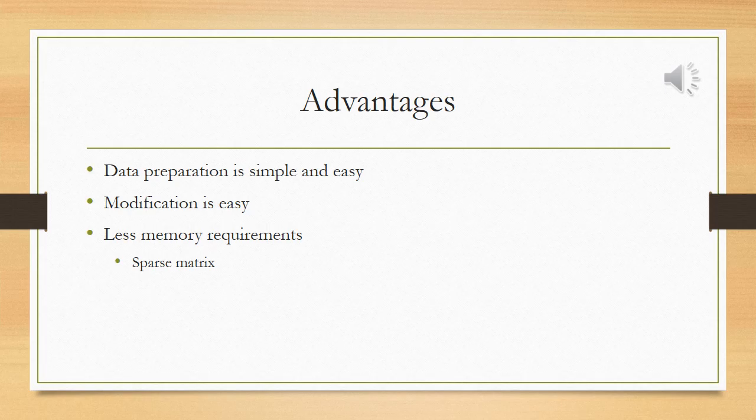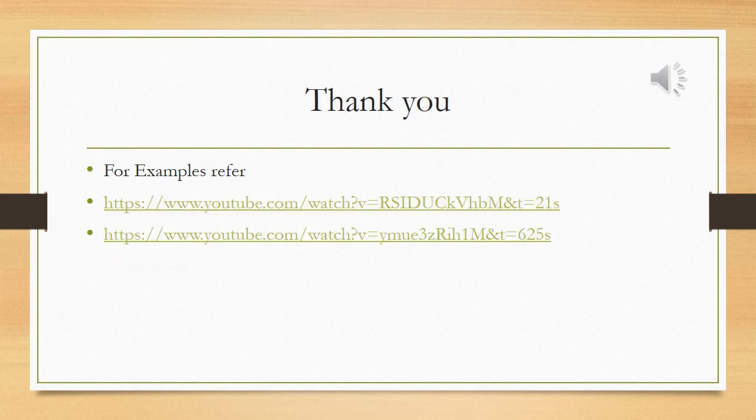So in order to solve the problems, if we have to study the relation between bus 3 and 5, the voltage and currents flowing in between, we just have to consider the row and column corresponding to 3 and 5. No other things, we need not take. So the computations and all the calculations become easy when we are using an admittance matrix. So I am winding up my section on admittance matrix.